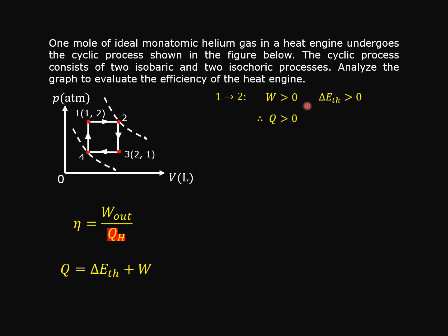Based on the first law of thermodynamics, if the internal energy change is positive and the work done is positive, then of course Q is positive. That means the heat flows into the gas in the isobaric process when the state changes from state 1 to state 2.